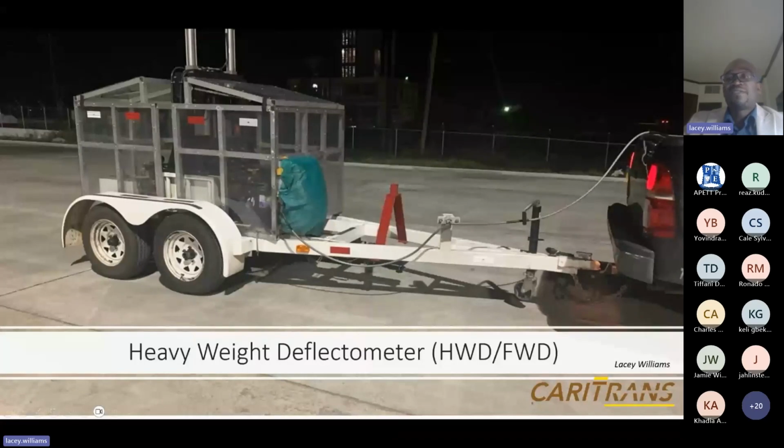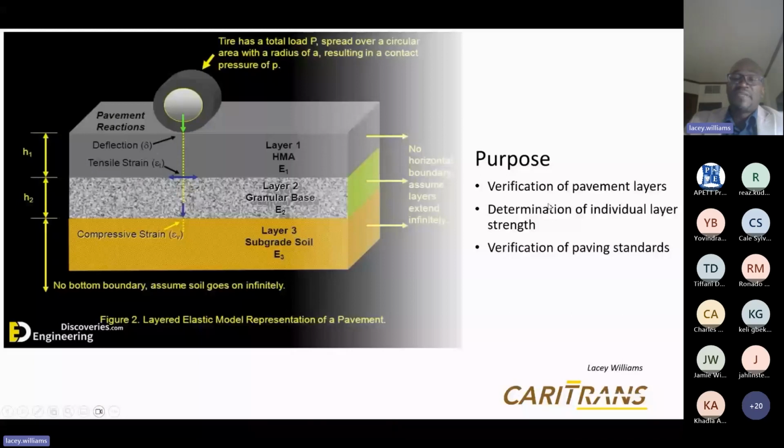So essentially, the FWD or HWD is used to verify pavement layers. First of all, whether the number of layers that you have, the individual layer strength, and of course, just recently we were on a project where we were actually verifying the pavement standards as to whether the individual pavement layers, subgrade, subbase, base course, and asphaltic base course, actually met the design standards as set out by the design consultant.